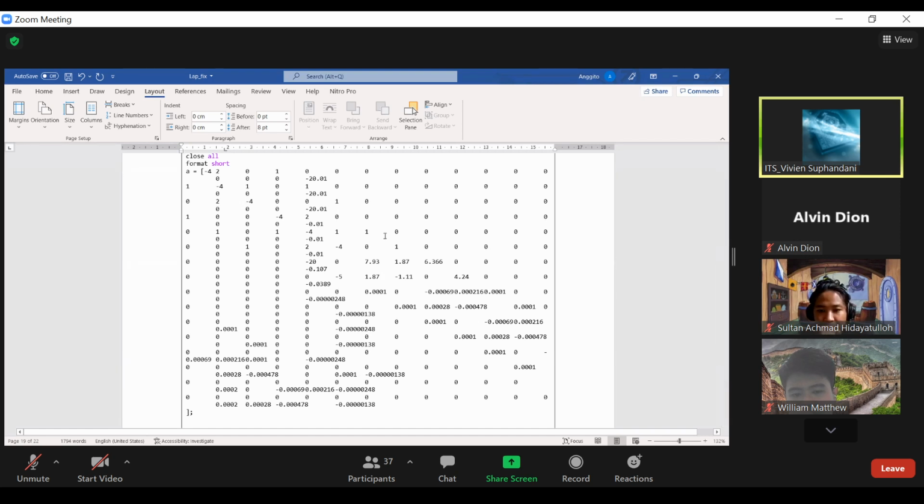For example, you multiply the equations from the cylindrical coordinates by 10,000 or 100,000, so that you have approximately the same order as the value of the coefficients from the rectangular. With that, I think the case when you use Gauss Seidel is because of the rounding error.